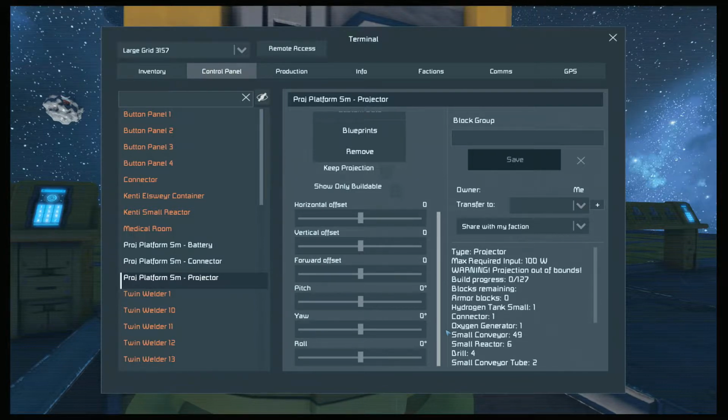So imagine the control stick. Pitch is pushing the stick forward or pulling it back towards you. Yaw is your rudders. So you are literally, it's flat, but you are shifting it from side to side around that z-axis. Roll is taking that stick and moving it to the left side or the right side.